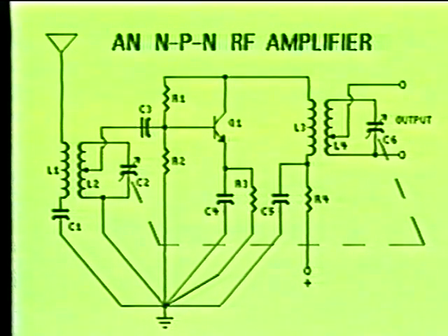Notice that all the common leads of the RF amplifier stage are brought to one point. This is a very important thing when designing high-frequency circuits. Using a single ground point becomes a necessity if minimum interaction between stages is to be obtained. Also, all leads should be as physically short as possible. Otherwise, the long leads may produce a self-sustained oscillation, or they may interact and cause oscillations in other stages.